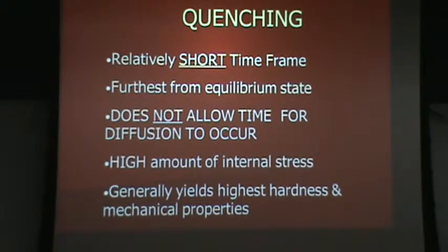It's important to note that during quenching, you tend to have a lot of stress developed, and that can lead to cracking. So one of the things that I deal with in my job is looking at parts that crack and trying to understand why they crack. Sometimes that's related back to the stresses that develop during heat treatment. Sometimes it's other reasons. These stresses can be magnified with different types of geometry.